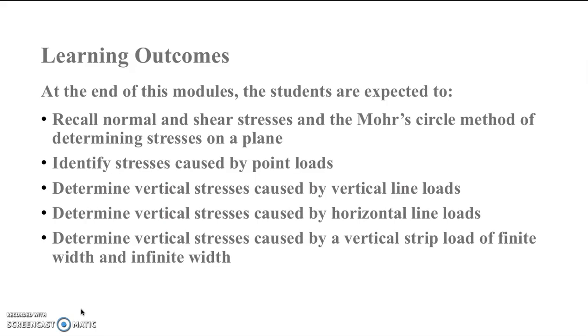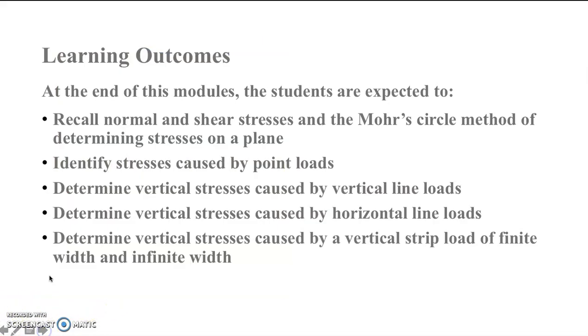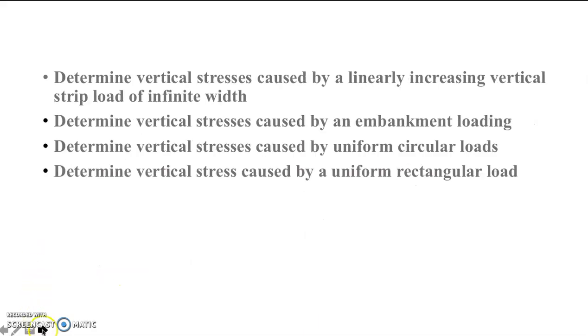circles method of determining stresses on a plane, identify stresses caused by a point load, determine vertical stresses caused by vertical line loads, determine vertical stresses caused by horizontal line. Determine vertical stresses caused by a vertical strip load of finite width and infinite width. Determine vertical stresses caused by a linearly increasing vertical strip load of infinite width.